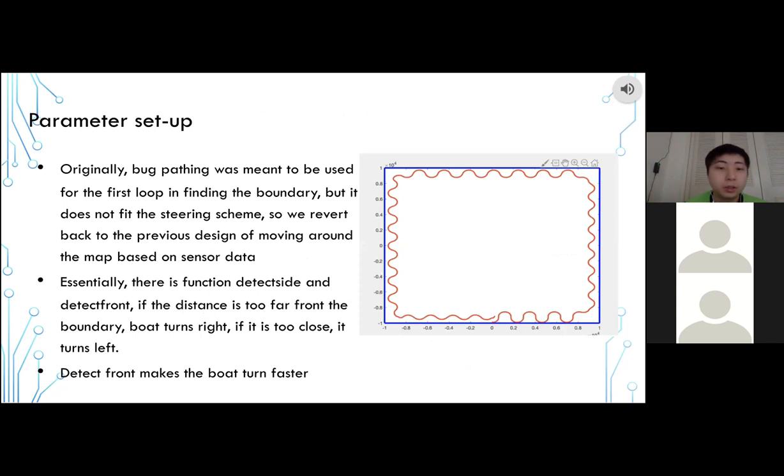Originally, we thought that we should use the robotic toolbox to keep the boat constantly parallel to the boundary while mapping the boundary. But when we did it, it doesn't do so well with sharp corners, and when it's always parallel, the data points from the back sensor will be very limited as the mapping poses would only rely on the side sensors and the front, possibly creating a significant error when mapping the boundary. So, we ultimately decided on this solution, as you can see on the graph.